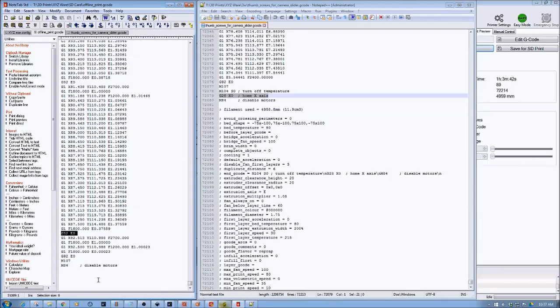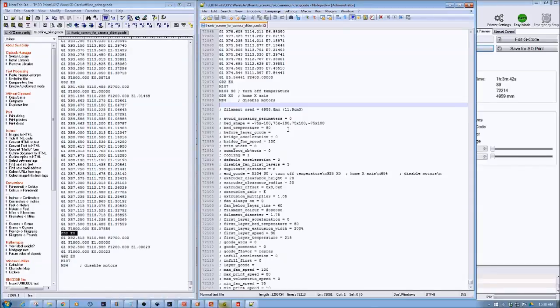I remember Chuck Hellebuck on his channel talking about adding something in his reflashed version of the 1.0 to move the bed down, and so I'm going to take a look at that, so keep that in mind. The other thing to know is over here. You see this where I've got my mouse hovering, this blank line. You cannot have any blank lines. So I tried some stuff last night after the last video, and it failed miserably. The printer kept restarting itself. So I went to Google and I found the answer relatively quick. Any blank lines in the G code causes the printer to reset. So you have to make sure you remove all the blank lines.